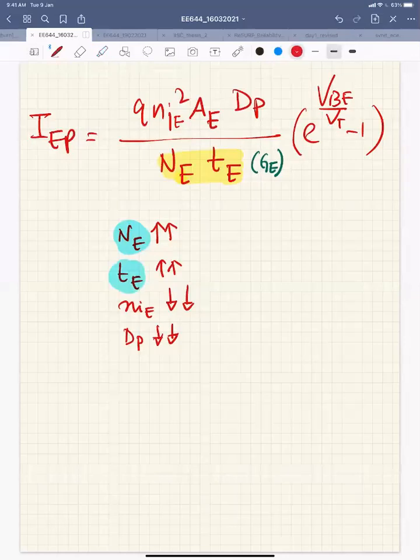And to increase the emitter thickness, we go to a polyemitter, right? Because we could not really increase the emitter thickness otherwise; your base will be far away from the surface, right? So you use polysilicon, right? You deposit polysilicon. Your emitter is mostly made of polysilicon, and when you move to a polyemitter, then you could deposit the emitter, and deposition can be controlled. So you could go to any thickness possible.